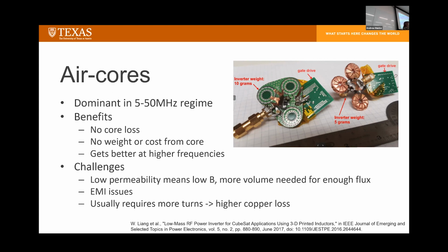Like I said, they don't have any core loss. They also don't have any weight or cost from a core. And air cores typically do get better at higher frequencies due to their permeabilities and things like that. And then I have an example here of a team that made some in-plane PCB inductors, and also 3D printed inductors.